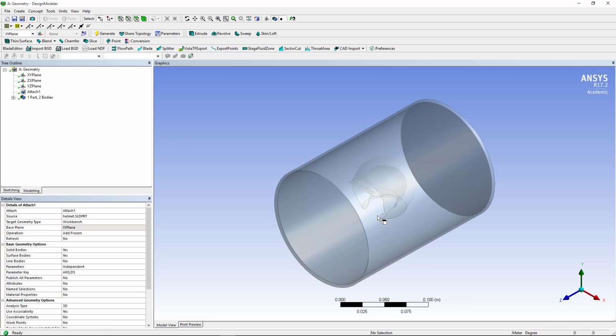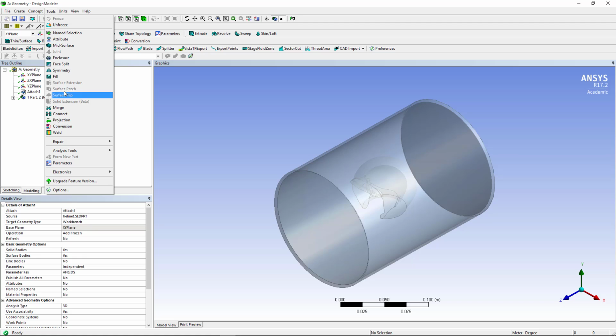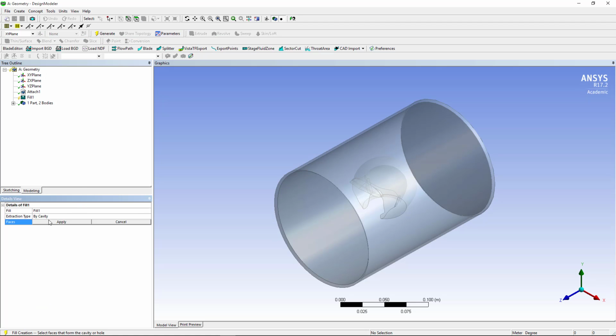You see the helmet is inside there. It's all capped off. So the first thing you need to do is go in here to Tools, and we'll go to Fill. And we'll change from cavity to bicaps. All I did was double click there, or you can use the drop down menu to go to it. That's all you need to do, and then go ahead and generate again.